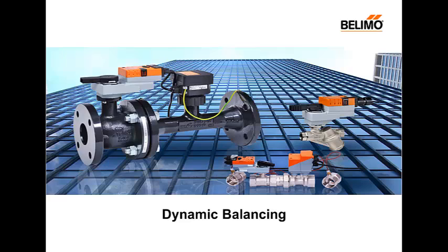Today's topic will be dynamic balancing. Normally on our webinars we do more product-focused subject matters, but today we will be discussing a key point in the hydronic balancing of your building. And what we'll talk about is how pressure-dependent valves leave your building statically balanced, while a dynamic balancing comes only from using pressure-independent style valves.